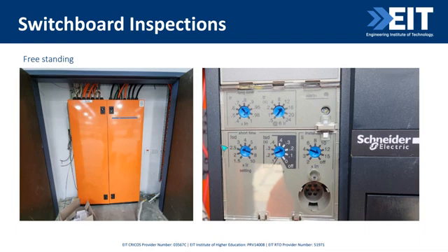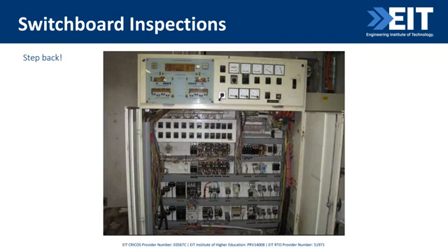If you were to look closely at a circuit breaker, you might find that it has the ability to set the settings. So perhaps you want to check those settings in your inspection to make sure they are correct. If you see something like this though, my suggestion is that you don't go near it and that you stand back from something as old and as exposed as this switchboard.